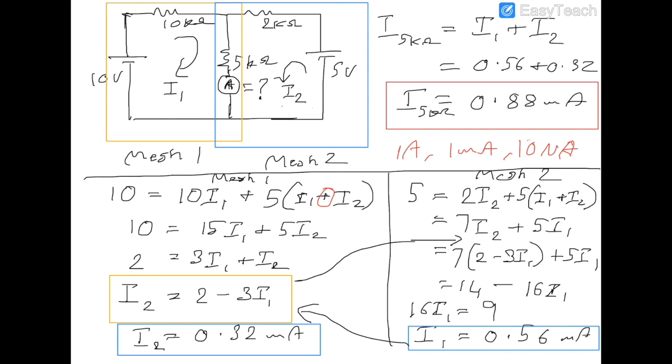Right? So you got three options. So which resistor do you pick? How do you know what's the current flowing through that? So if you do your mesh analysis, you know the current flowing through it is 0.88 milliamperes. So it's pretty much sufficient to select something slightly higher than 1 milliampere. So that is going to be a correct option to choose.